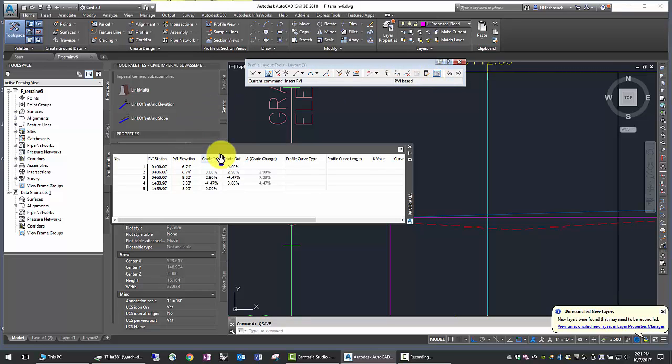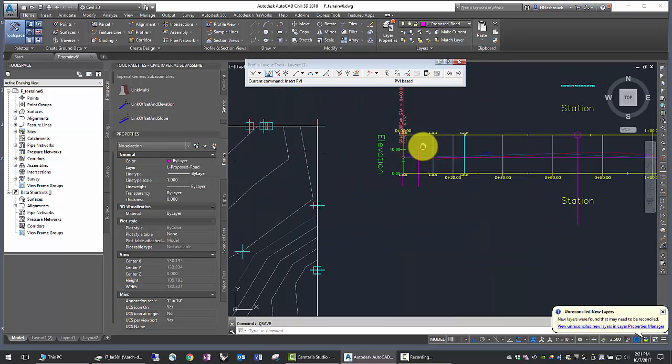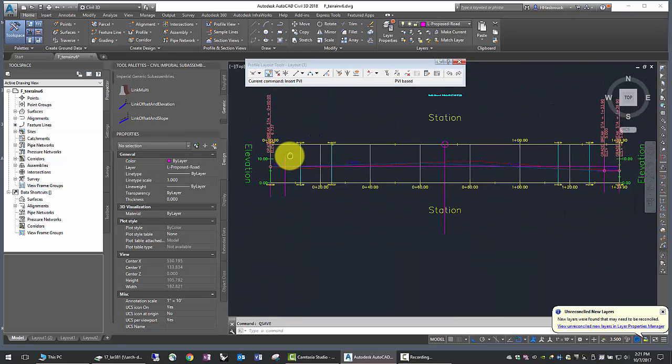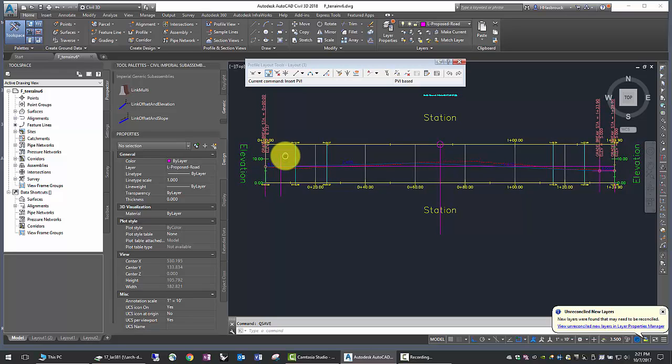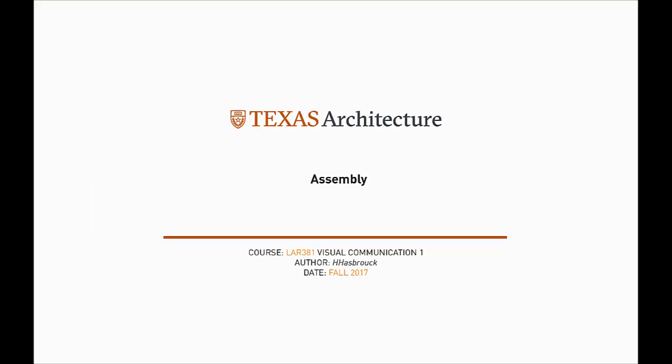Now I'm going to show you the table editor here. You can see where we begin at 0, and these are the slopes. Excellent. Now, in earlier things, I actually changed. There's a 0% slope, and then I added 2% slope from that. Let's call that the 0% slope landing. But as you know from your tech course, it should have some sort of a grade to it. It has a cross slope.